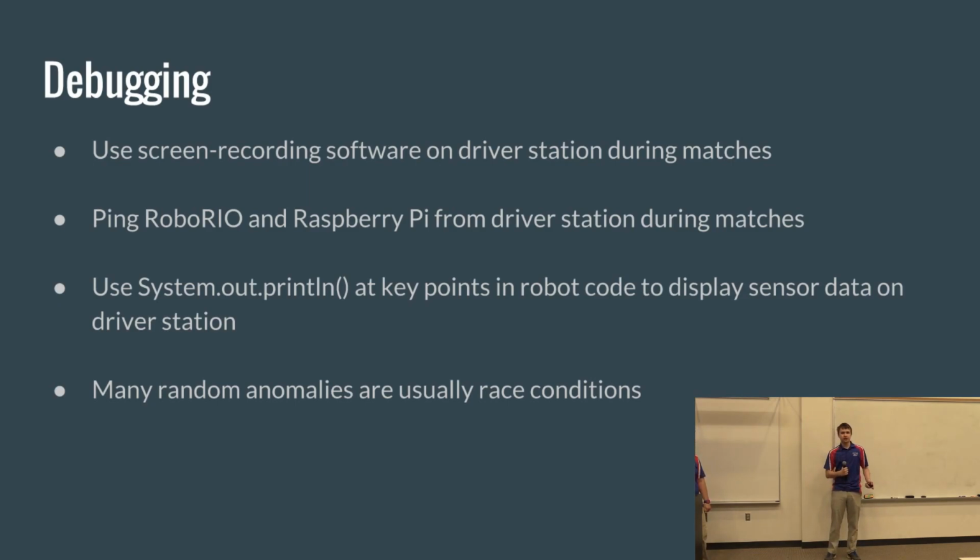What was actually happening is, when you boot up the entire robot, everything powers on and starts its boot-up process, and the Pi would finish before the IP camera was ready to run. As soon as the Pi was finished, it would go, okay, let's pull this IP camera and start doing our stuff. When there was no IP camera to pull, it would crash. Since he didn't realize it was the IP camera causing it, he would simply reboot his Pi, which would then find the now booted IP camera and work properly. So like Rashad said earlier, you want to have pings to ensure that what you're looking for is there before you access it.